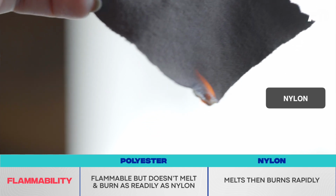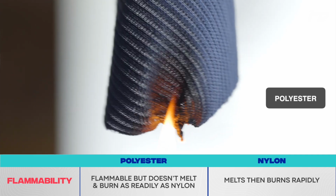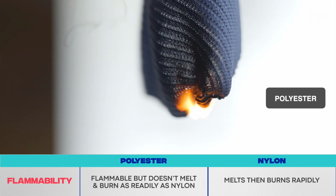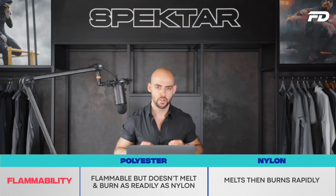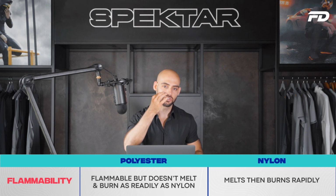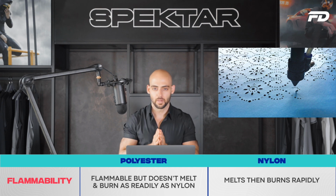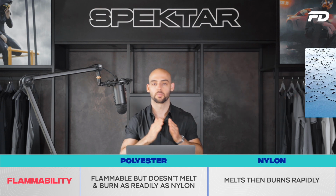On the flip side, polyester is also a garment that's quite readily flammable, but it doesn't melt and burn as readily. So I'll give you guys a clear example. Let's just say you're looking to create a laser cut pair of leggings, and when it comes to laser cutting, you're going to apply a laser that provides a lot of heat to the surface. So when it comes to your selection, is it nylon or polyester?